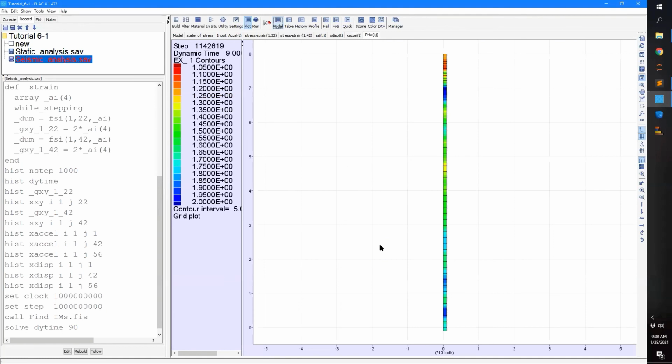And so what we're showing here is the peak acceleration during shaking. What we see is that there's a few locations where we have really high accelerations at the top of the dense sand layer, relative to the other locations. This is in terms of meters per second squared, so just around 0.2 g. And then we have this soft layer, so the deformations are larger above, but accelerations are lower because of the increased damping due to the yielding. That's something worthwhile.